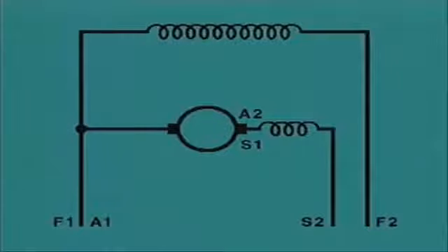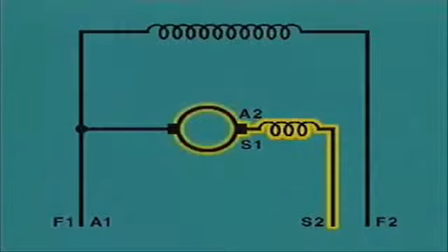So, according to the diagram, one meter lead should be placed on motor lead F1A1, and the other lead should be placed on motor lead S2. The current path being tested is from motor lead S2 through the series field to S1A2, through the brush, through the armature and the other brush, to F1A1. If the meter shows a reading, we'll know that the series field, the armature, and the brushes are good, and that the problem has been solved.